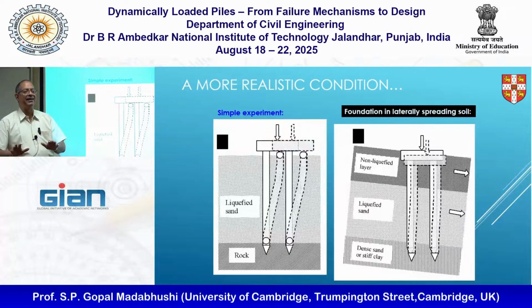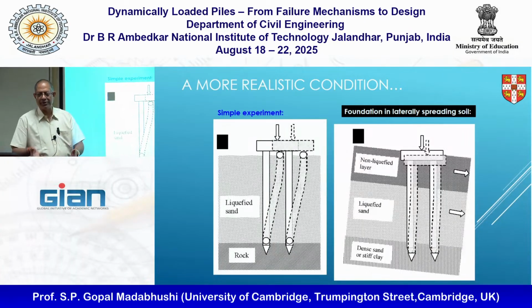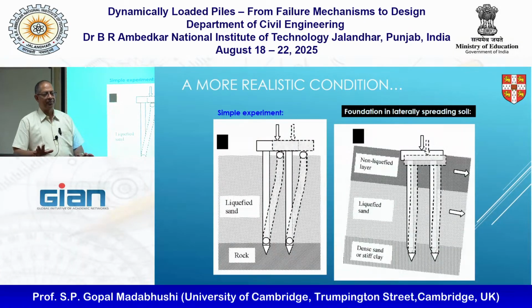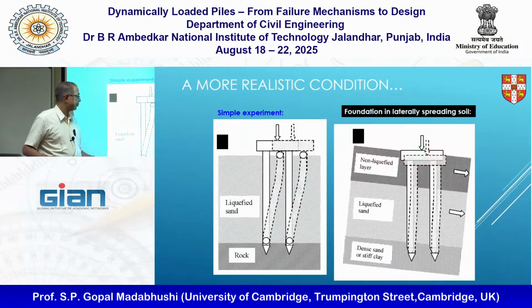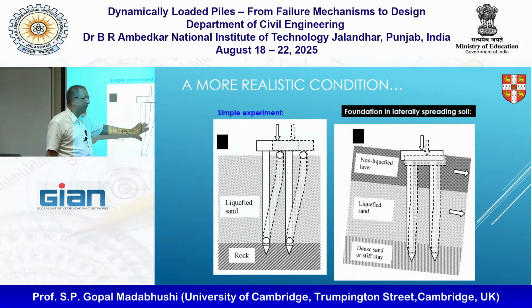If it is coming anything like 2 times or 3 times the load that the column is going to carry, they'll get scared. So what they'll do is start designing some struts, horizontal struts, to support the columns. So, a quick check, make sure that doesn't happen.